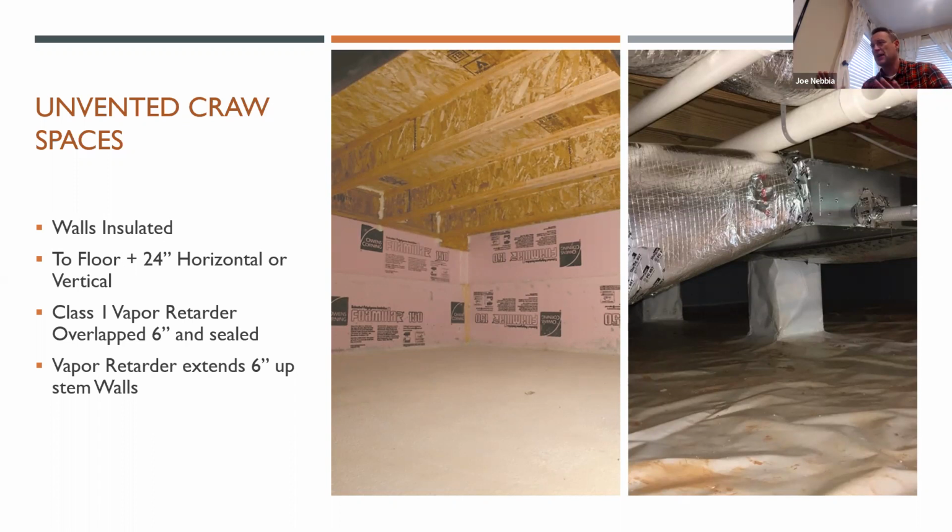There used to be this kind of weird thing in 2018 and earlier where the crawl space insulation requirements were kind of repeated in the prescriptive and mandatory sections. So most of it was mandatory anyway. It's now all required in all three compliance paths in 2021.